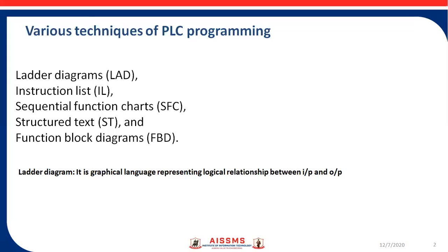Different techniques of PLC programming are ladder diagrams, instruction list, sequential function charts, structured text and function block diagrams. Ladder diagram is graphical language representing logical relationship between input and output.